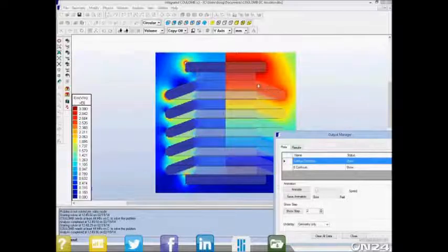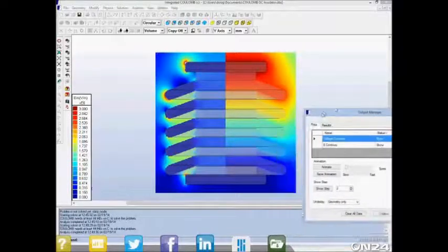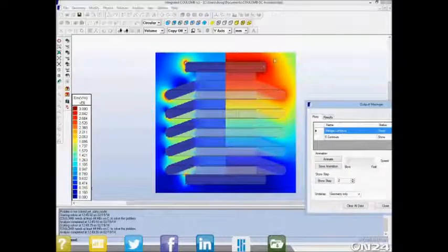Therefore, the sheds will push the voltage out. And so you see now the high voltage doesn't drop right around the top like it did. It drops more or less uniformly from shed to shed to shed. And as a result, the high field right at the edge of the top conductor is not so big. But notice that there are now substantial fields out at the edges of the sheds as well as in between the sheds.